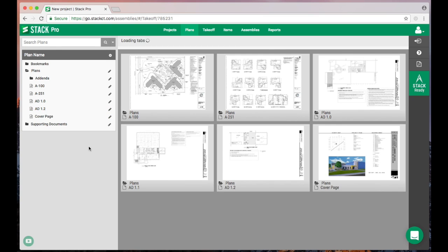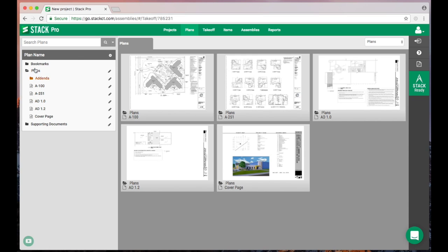Okay, so hide is a little quicker. It's going to save you that mouse click. It's going to remove it from the thumbnail view. The nice thing about hide is if you ever want to bring it back, you're just going to go back to the little gear wheel and you can bring back those hidden pages. So a real quick way, it only takes like half a second per page to run through and get that cleaned up if you want. But let's hop into Takeoff.